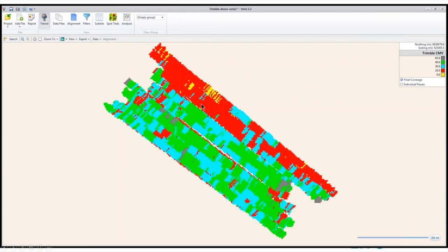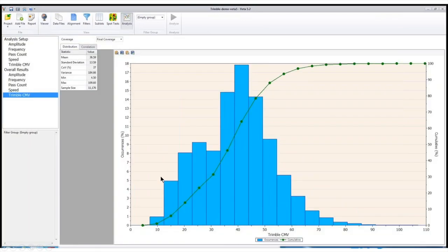Here's a very interesting plot that you can see on the top. There's a red spot. That's where the moisture content is 2% higher than the OMC. And the middle part is the OMC. On the left-hand side, that's 2% less than the OMC. The red spot here is a soft spot, the treasure hunt that Jeffrey mentioned. That's where the contractor had buried a tire underneath, but it was detected by the IC roller. So this is the analysis.